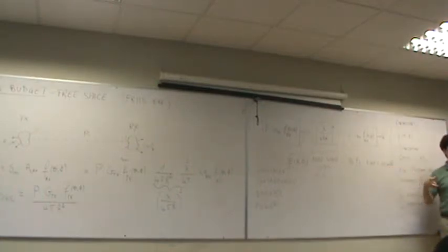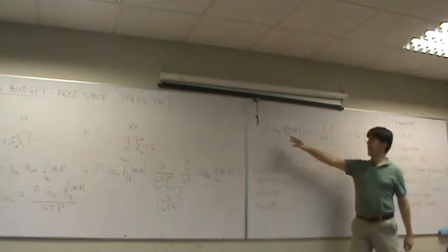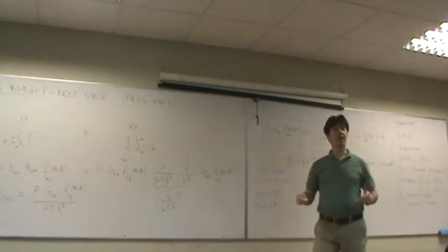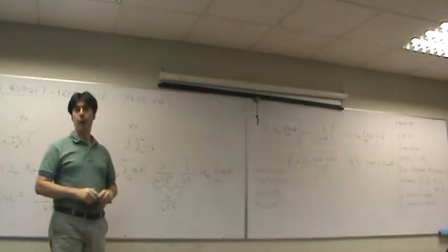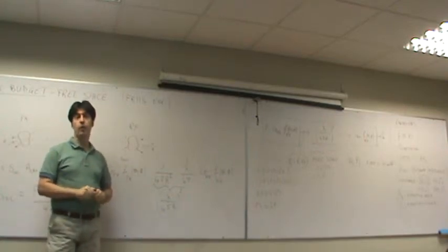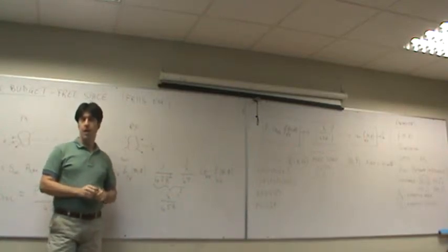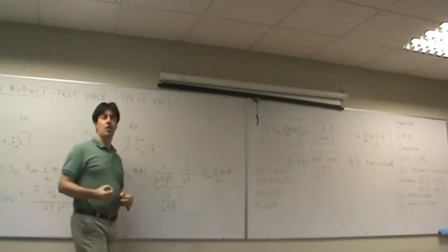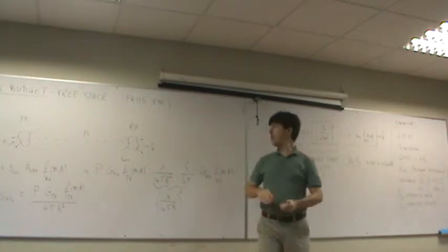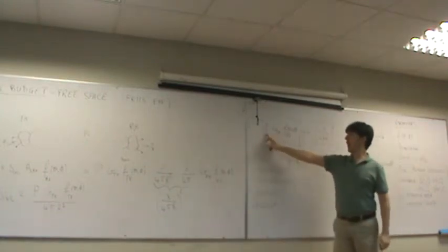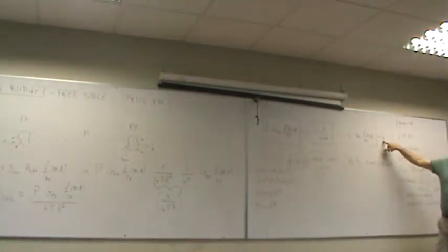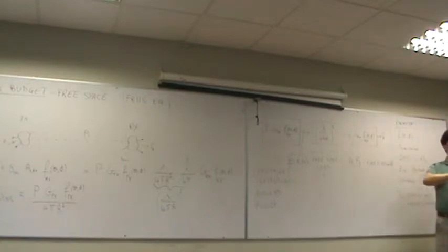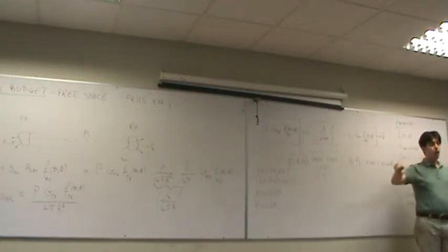It means that you cannot cheat. You cannot replace the antenna with an antenna that has a higher gain. If you do this, you have to reduce the power of the transmitter. Otherwise, you are violating the law. And the basic concept behind this is that whatever combination you choose between power and gain of the antenna, if this is the limit, you will always have the same power at the receiver. That is, the coverage range of your Wi-Fi access point will always be the same.